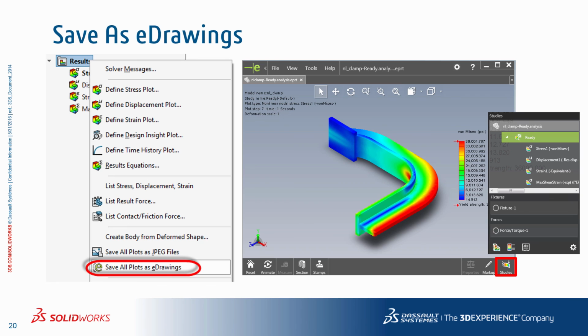Also, since all the plots are now available, I can toggle back and forth between, let's say, the stress plot, displacement plot, factor of safety plot inside eDrawings very easily. I can even turn off fixtures and loads plus superimpose the mesh on top of the contour plot. So this is really a very cool yet very powerful functionality or feature available to you inside SOLIDWORKS simulation.